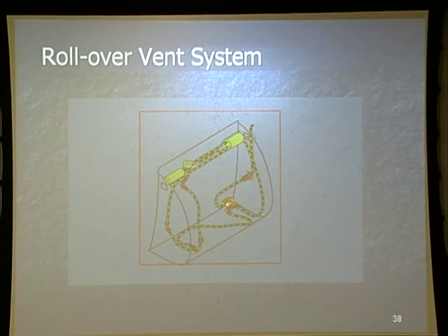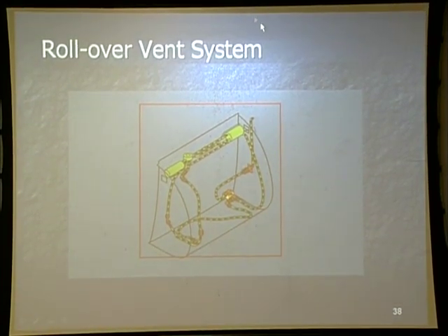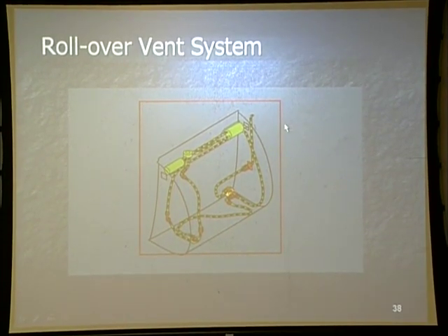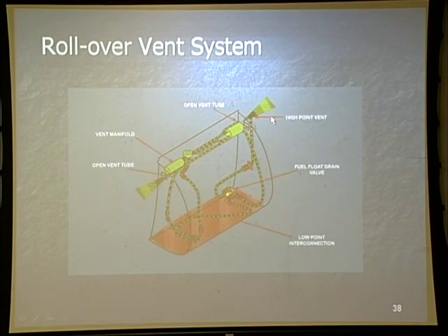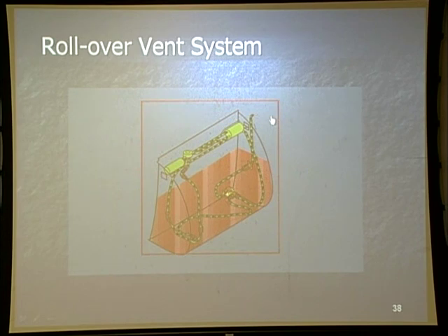So what it looks like is this. First off, this is showing you an empty tank. What do we have to do? We have to put fuel in. What's in the bladder right now? Air. So we have to let the air out. So as fuel comes in, quite simply, what's going to happen is it's going to force that air to the top, causing that air to be vented out so that fuel can go all the way up. Agreed?